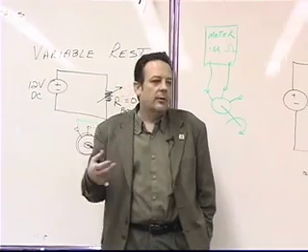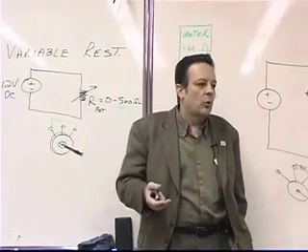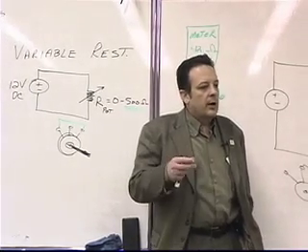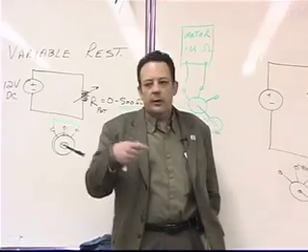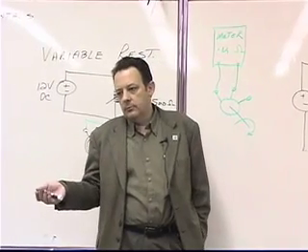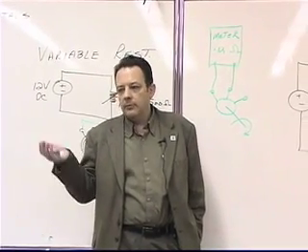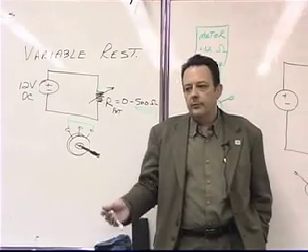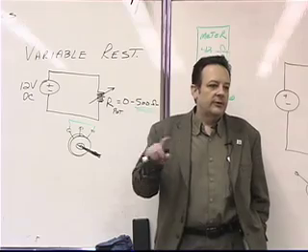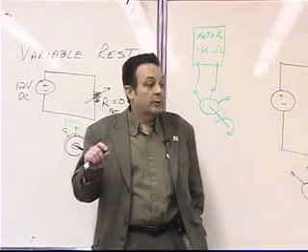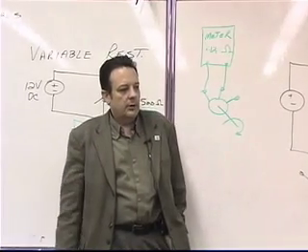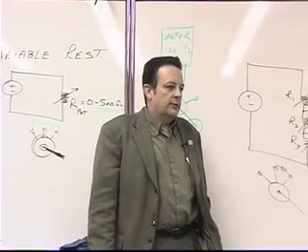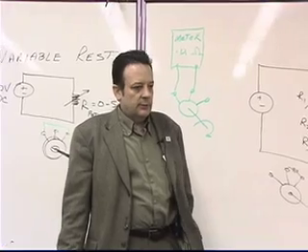You're generally not going to find rheostats that are rated for 0.5 watts. On the same hand, you're not going to find potentiometers that are rated for 5,000 watts. If you're looking for some kind of a variable resistor that's rated for 5,000 watts, you're almost always going to see that described as a rheostat, not a potentiometer. Okay? But really the function of it is not much different.